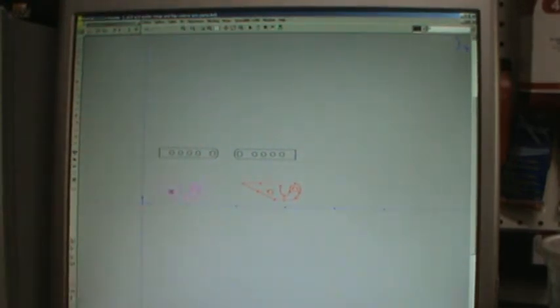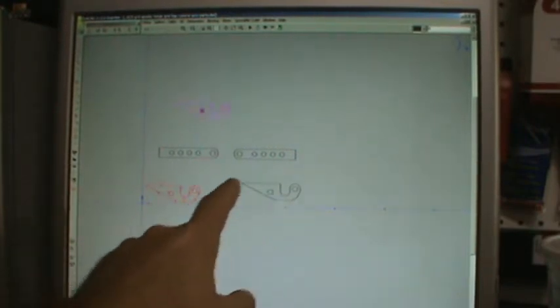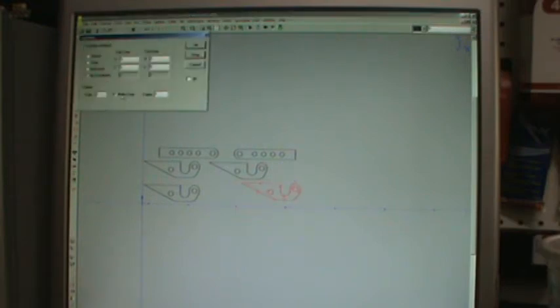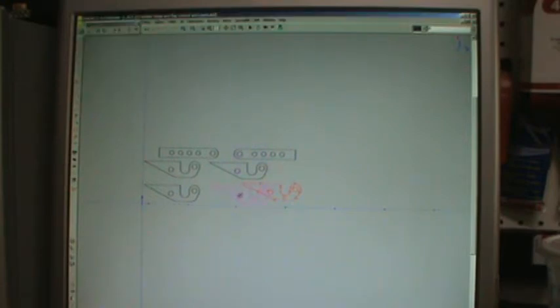So put that where you want it, click, and now you have your part, the original part, the part you just wanted, and then you have another ghost part. So we can take this one, and we'll cut out 4 of these just for some extra little extra parts to have there. And I'm going to highlight this one. I'm going to do the same thing as change and translate, but I'm going to unmark or uncheck make a copy, and then drag it, and then place it right here so they're kind of all in line.